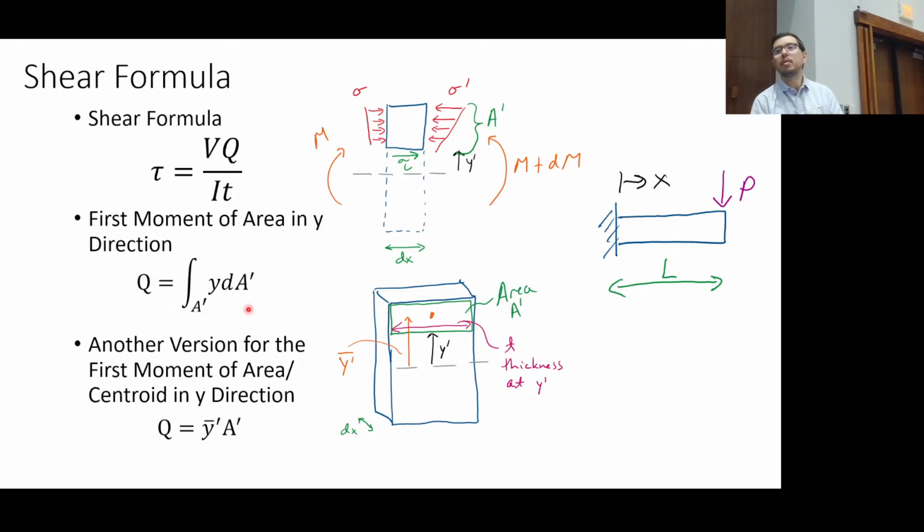And of course, we can hollow it out. The I-beam has a more complicated calculation, but again, I wouldn't recommend doing the integral. I would recommend just looking at an I-beam as a rectangular cross section minus a couple of rectangles.